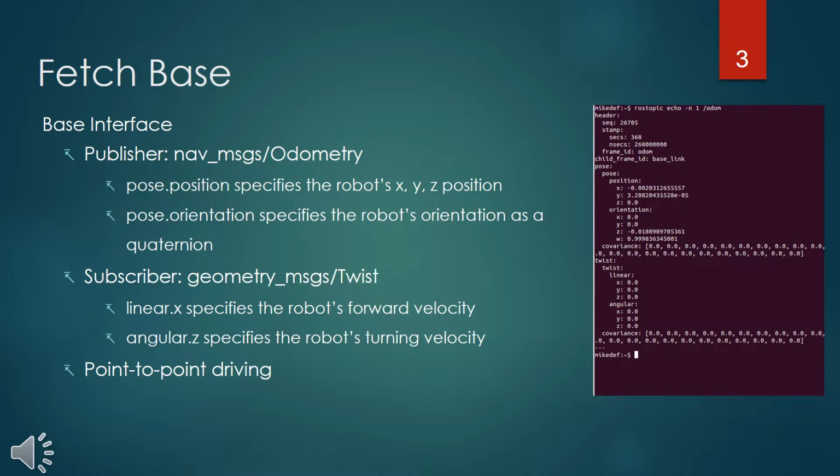For our project, we created a point-to-point control algorithm for the base using the messages previously mentioned. The algorithm takes in an X, Y position as a target location to drive to. It then calculates the angular error from its current heading to the target and rotates by that amount. The desired max speed is taken in as an argument when rotating, but the base will slow its rotation as it begins to face the target to minimize overshoot. The robot will then drive forward to the target.